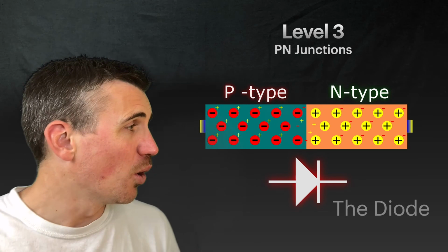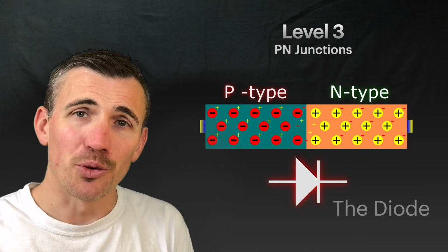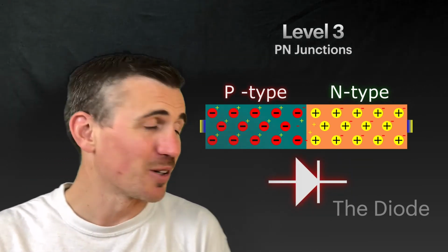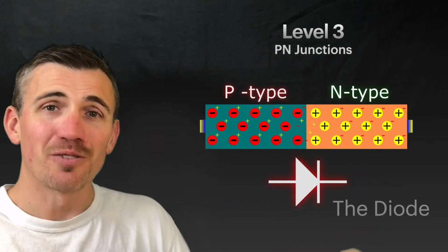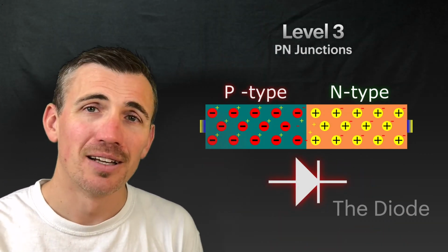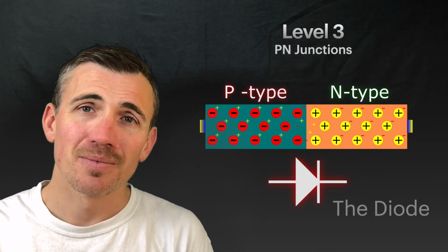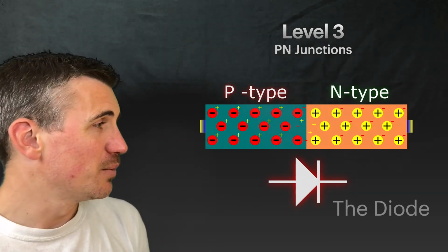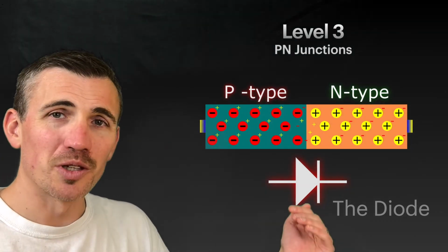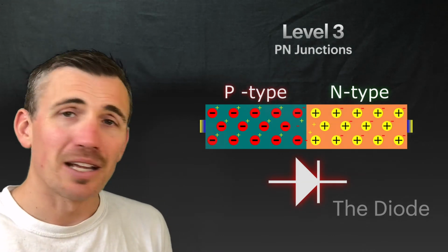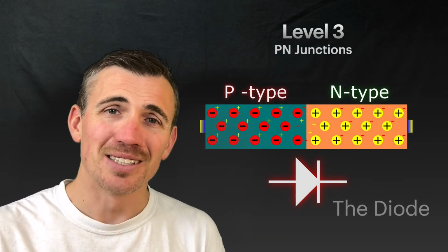As long as we're over this barrier voltage, the diode drop voltage, as we'll call it, we actually get current flowing. And below it, we get nothing. This is a nonlinear device. It doesn't obey Ohm's law. We don't double the voltage and get double the current. It's kind of all or nothing in this model.